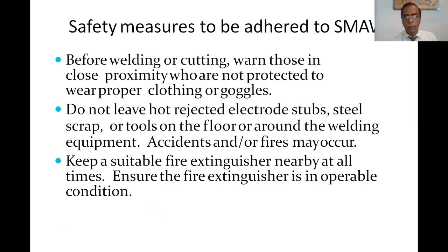Before welding and cutting, warn those in close proximity who are not protected to wear proper clothing or gloves. Do not leave hot rejected electrode stubs, steel scraps, or tools on the floor or around the welding equipment. Accidents and fires may occur. Keep a suitable fire extinguisher nearby at all times. Ensure the fire extinguisher is in operable condition.